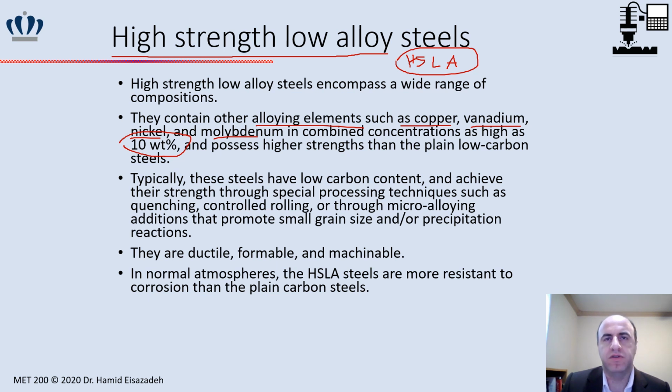Because of these elements, we can do various processing techniques such as quenching, rolling, and this process can increase strength through promotion of a small grain size. As you know, the smaller grain size gives you higher strength.